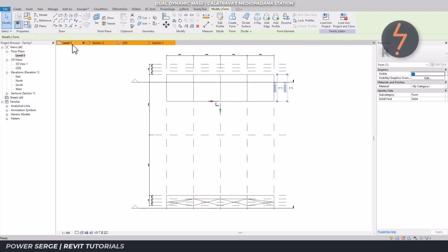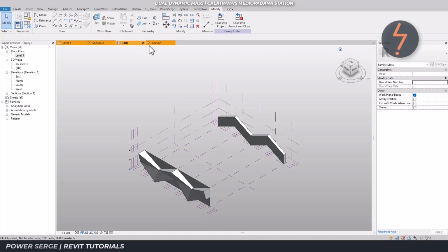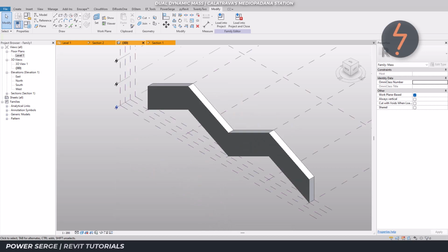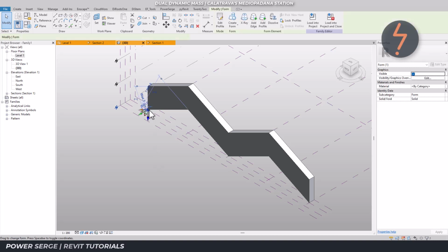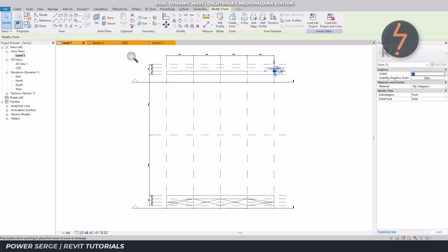And just as we did before, we interchange between views to drag the coordinates icon to manage our extrusion. Then rotate the view cube so that we are facing the form, and zoom in to manipulate the vertices. Just keep in mind that the selection points are now inverted. I should point out that you can by all means move the coordinate icon in the 3D view. I just prefer using the plan view to ensure precision.